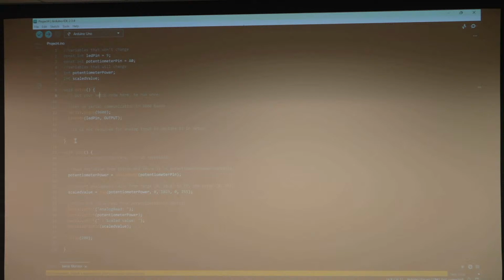So then the second part of the structure, so first the variables. Then we have the void setup here. The void setup is basically the first thing that runs in a robot. So everything that we need to set up a robot is going to be in that function, including, first, the pin mode, which is really, really important. So the first parameter is going to be the pin number. And then as a second parameter, we're just going to tell Arduino if that pin is going to be using an input or output component. That's for the pin mode.